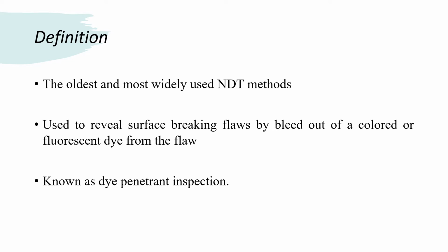This penetrant inspection utilizes the natural accumulation of a fluid around a discontinuity to create a recognizable indication of a crack or other surface opening defect. Capillary action attracts the fluid to the discontinuity as compared to its surroundings.